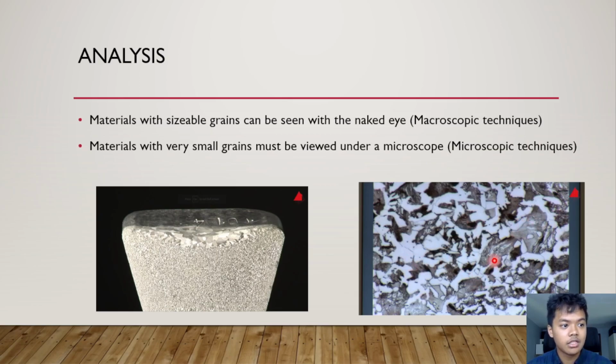Without etching, these structures, these patterns would not appear under the microscope or with the naked eye. That's why we need to etch our specimen before viewing it.